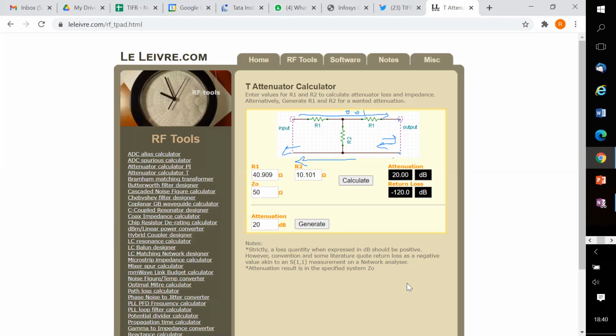So if I measure the reflection coefficient here with different boundary conditions on the other side, it will actually look very similar to 0, because that is anyway what you want. So when the attenuation becomes larger and larger, the role of R1 and the 50 ohm which is connected here becomes less and less from the point of view of matching to 50 ohms.